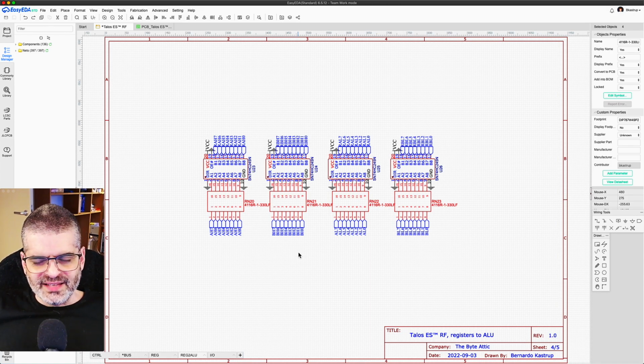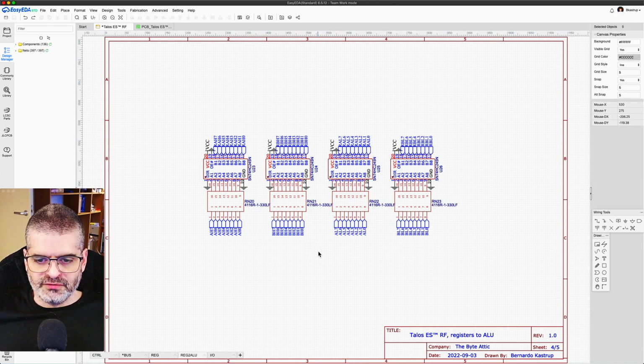But I regret that, and the reason is the impedance mismatch of the backplane connector, which produces its own reflections. So I put the 33 ohm resistors here to absorb the reflections from the backplane connector on the driver side. And in the case of the flags, the 6 flag signals from the ALU, they don't have these 33 ohm resistors on the driver side, on the ALU board. I forgot it, or I decided not to do it and then I regretted it.